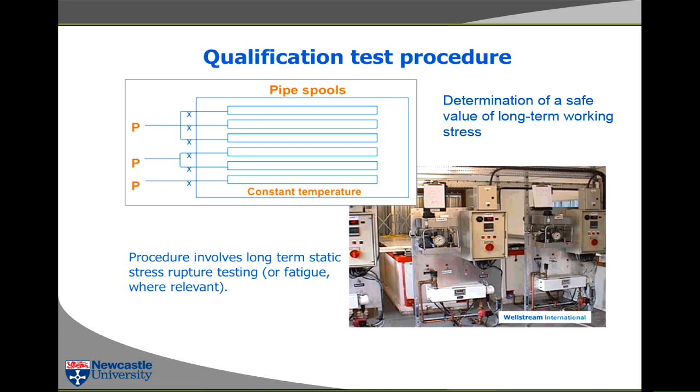Right, we talked about qualification testing of thermoplastic pipes. Actually, all qualification testing of non-metallic pipes involves similar procedures, because these pipes all fail by the process that we call stress rupture or static fatigue. So you apply a load, and sometime later the sample fails. So it's a time-dependent yield, or if you're unlucky, it's a time-dependent growth.